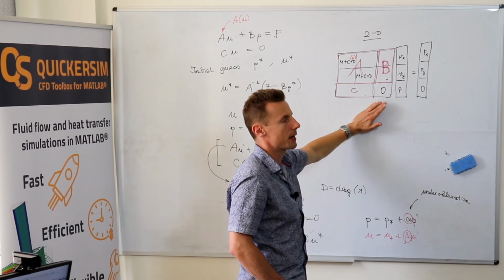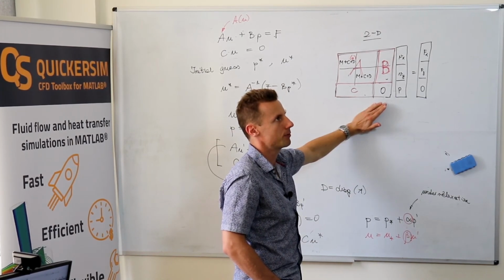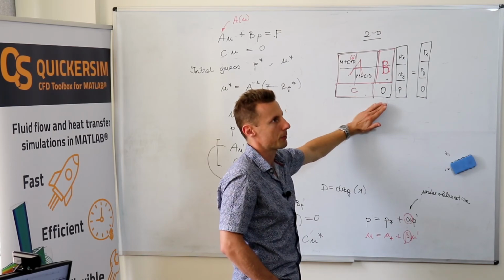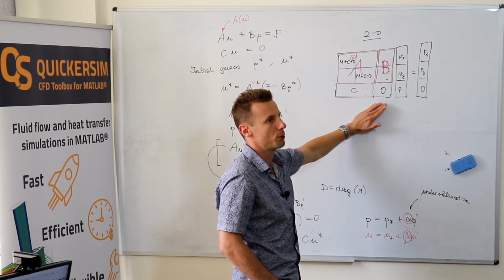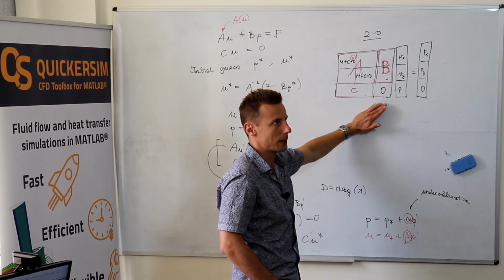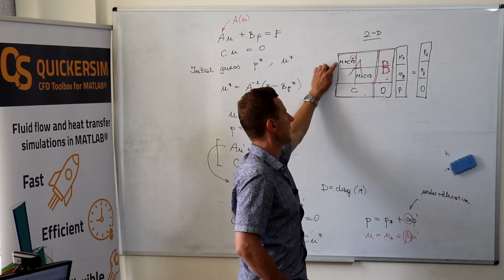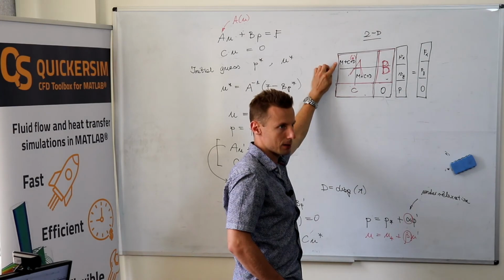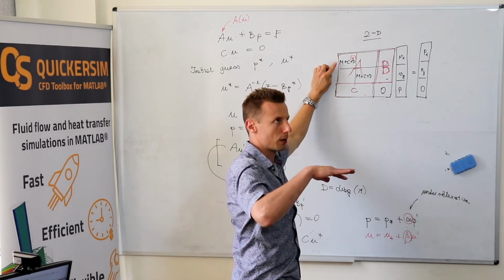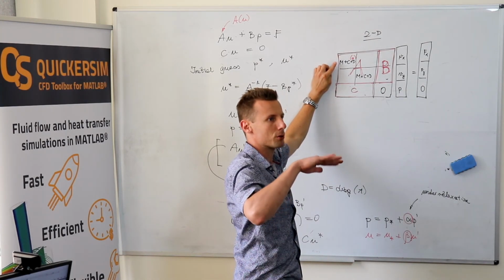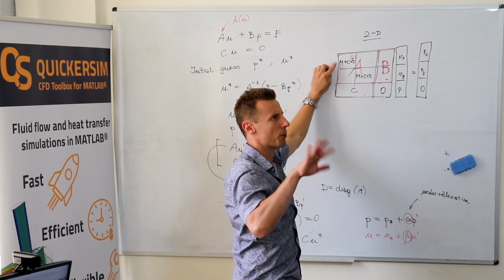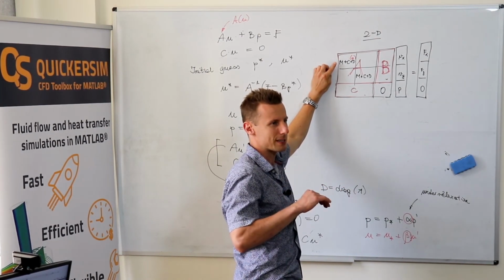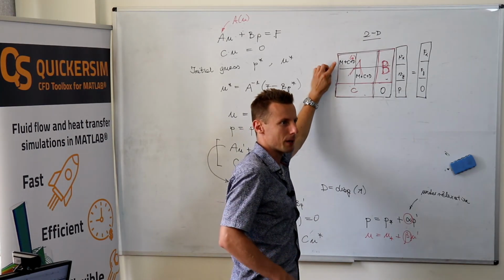The problem is that I cannot give you the proper proof or derivation right now, but I remember that you can develop a proof of convergence of such a splitting scheme to the right solution if it's an unsteady Navier-Stokes case, because the proof really monitors how the norm of the divergence field is updated or how it develops.